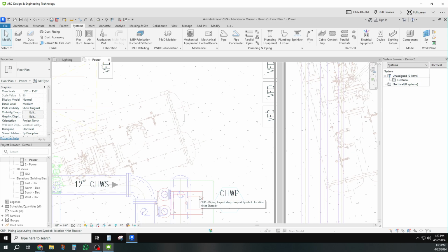And so that's going to take 480 volts, 3-phase. And you're going to see in Revit there's one called 460 volt, 3-phase, and that's what we're going to put in. Okay, so I need to have a power panel that I can hook junction boxes to so the wires can come out and drive the motors.